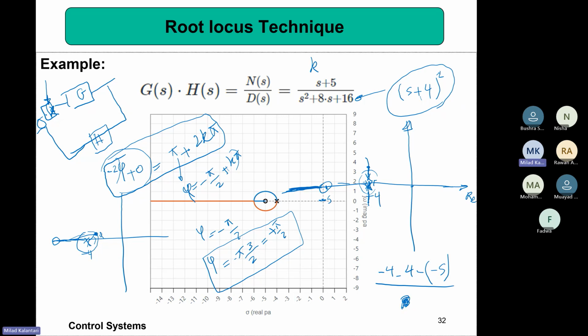When you are looking from far, it looks like there is just one pole. One of the zeros is kind of canceling a pole, so it remains only a single pole when you are looking at very far, right? When you are looking at very far at this system, you see that one of these poles and zeros may cancel, and it remains only a single pole.